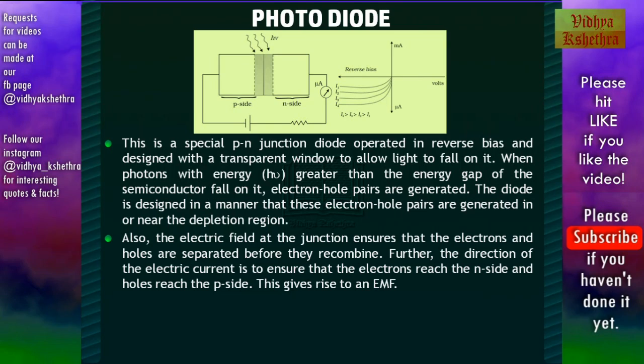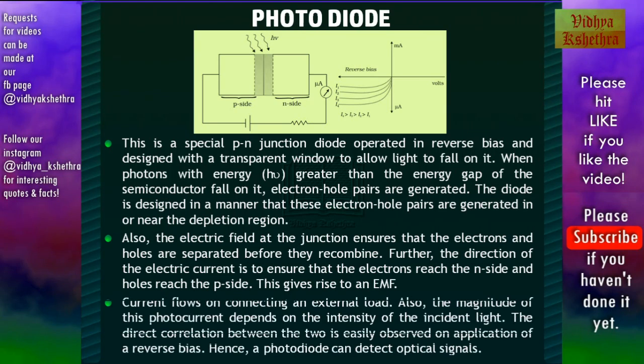Further, the direction of the electric field ensures that the electrons reach the N side and holes reach the P side. This gives rise to an EMF. So current flows on connecting an external load. Also, the magnitude of this photocurrent depends on the intensity of the incident light. The direct correlation between the two is easily observed on application of a reverse bias. Hence, a photodiode can detect optical signals. So, it can be used as a photodetector.